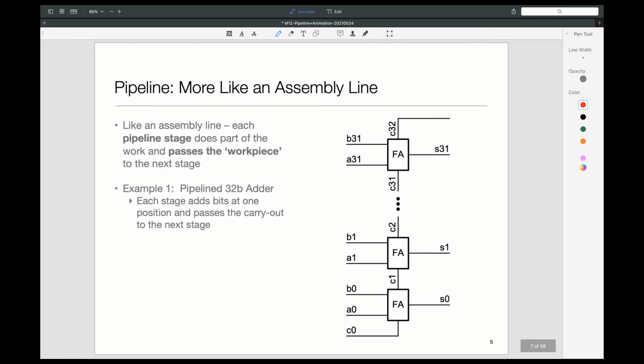If I have n bits, then the delay is proportional to n. Now, what is happening in this ripple carry adder? Every stage adds the bits and the carry coming from the preceding side. If you look under the hood, the carry was rippling through. The lower bit did its job first, handed over the carry to the next bit. It did its job, handed the carry to the next bit. So the carry was rippling like this.